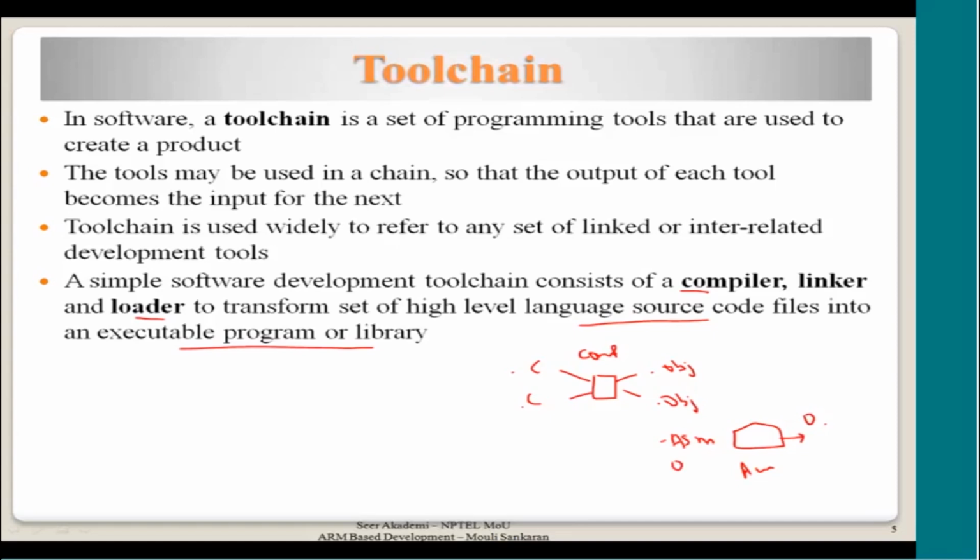The assembler generates an output file, which would be dot s. And then what do you do? All these OBJ files and the files coming out of this assembler, you can use a linker to link them all, to generate a linker file. The linker format is also there, so many things are there. And now we can actually generate an executable. When you say executable, then we know that the code or data, all those things, are placed somewhere in a memory. We know where it exactly goes.